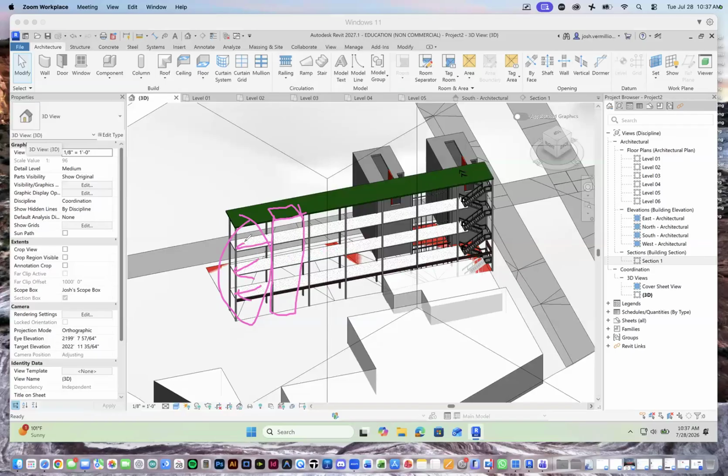Because what happens with a dead end corridor is you basically confine somebody to one point of egress. If I look on either end of this person, what we don't want is for them to get to this edge because there's a fire right here. They can't get to the stairs, and then they have to make a choice. Do I hope that the fire is suppressed in time, or do I jump and think I'm Superman?